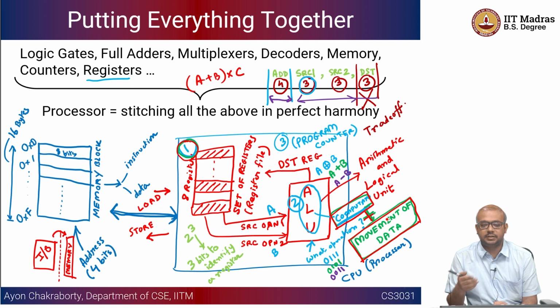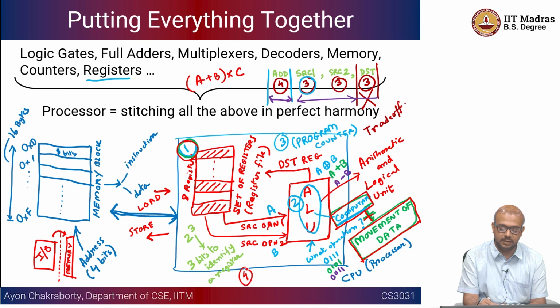The ALU computes this value A plus B. After you get the result, the value has to be stored in a certain register. You cannot do this before the ALU computes these values, in some random order, right? If you see this entire sequence of very controlled steps, what exactly happens in the CPU, what data is copied from what register to what place, what happens at the next instant of time, this entire thing has a very tight orchestration and control, and typically this is done by one of the most important parts of the CPU called the control logic.